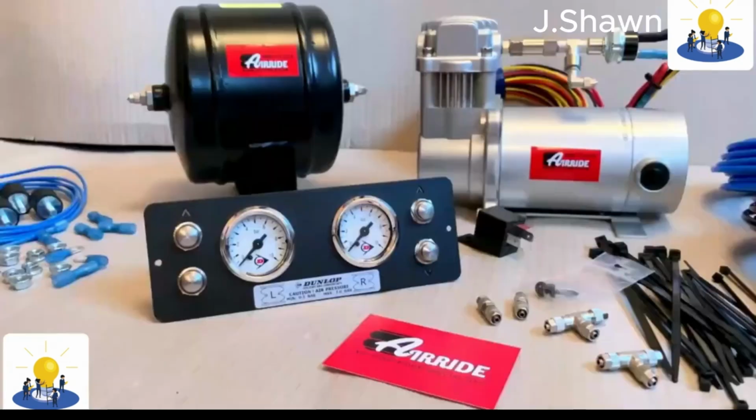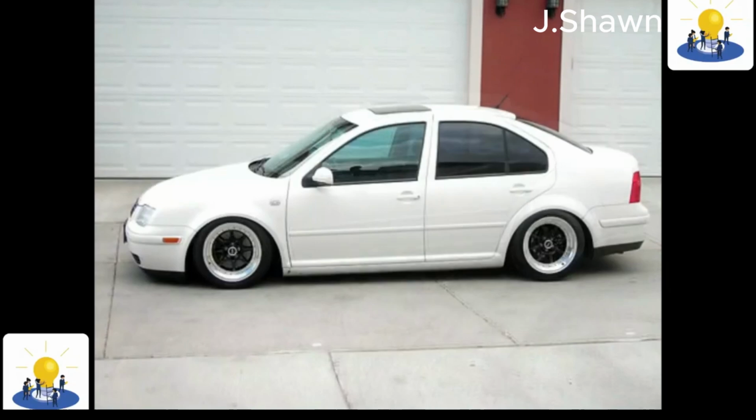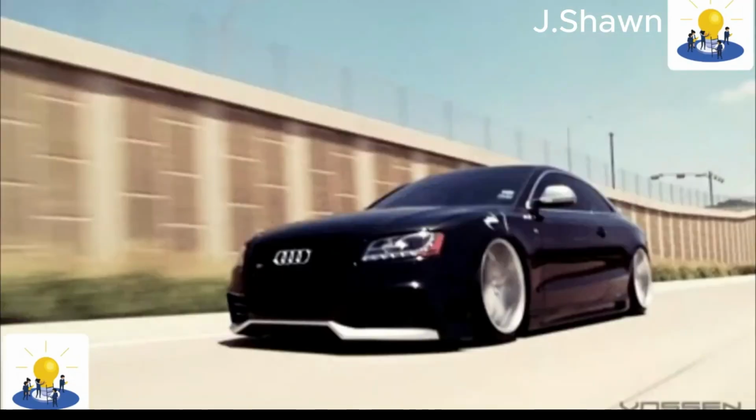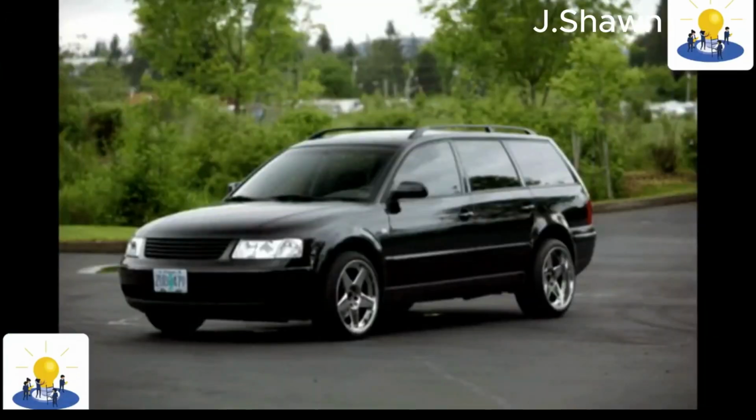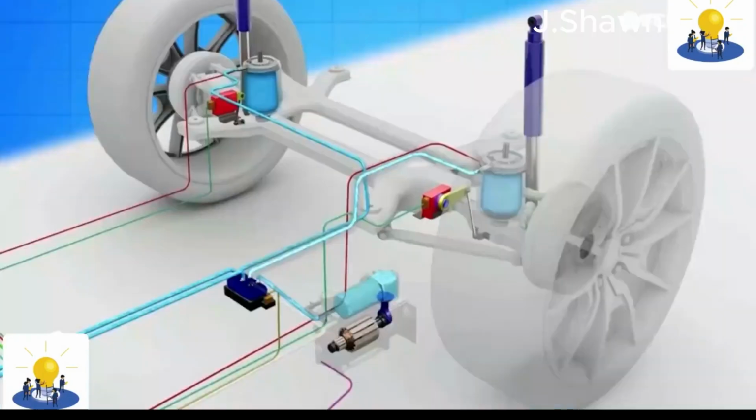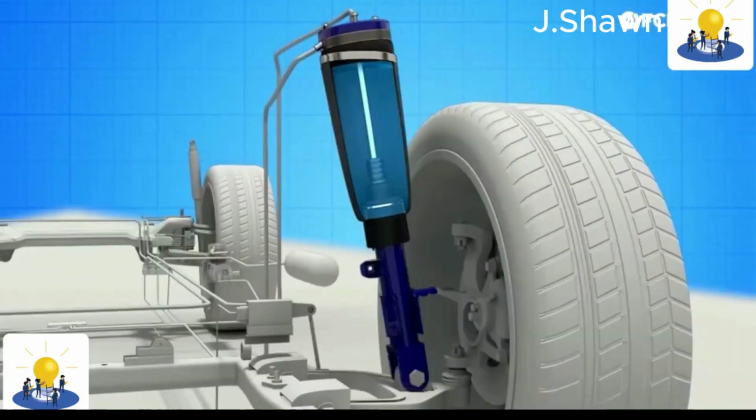Failure of an air spring may also result in complete immobilization of the vehicle, since the vehicle will rub against the ground or be too high to move. However, most modern automotive systems have overcome many of these problems. Airline failure is a failure of the tubing, which connects the airbags or struts to the rest of the air system, and is typically DOT-approved nylon air brake line. This usually occurs when the airlines, which must be routed to the airbags through the chassis of the vehicle, rub against a sharp edge of a chassis member or a moving suspension component, causing a hole to form.